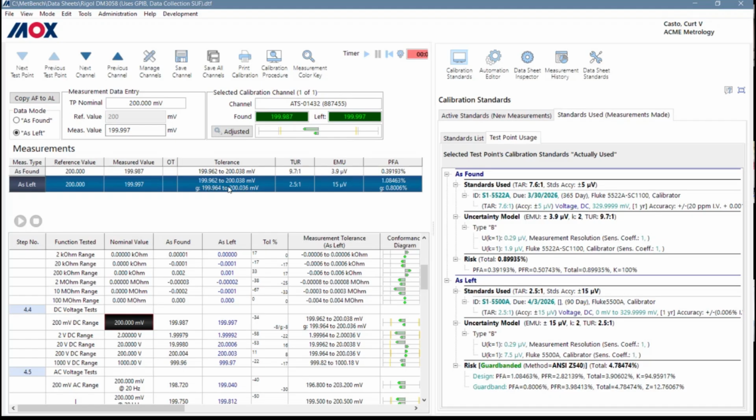Or you can do the Z540.3, and we use the RP18 iterative statistical method to actually determine the guard band multiplier. So what it will do is keep adjusting the guard band multiplier until it finds the guard band multiplier that just returns it to the target PFA. So you'll get just enough guard banding to get you back to your target PFA. So you can see that here, right? With the design tolerance, our probability of false accept was 1.08%, and then with the guard banding, 0.8%, back to our 0.8%.